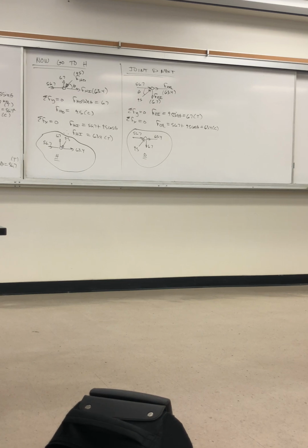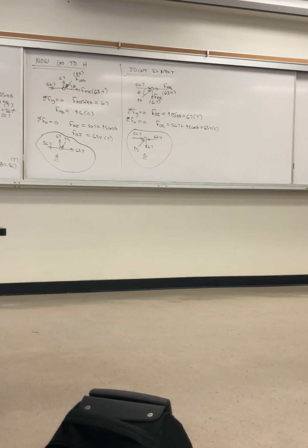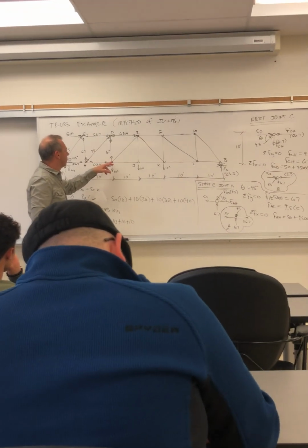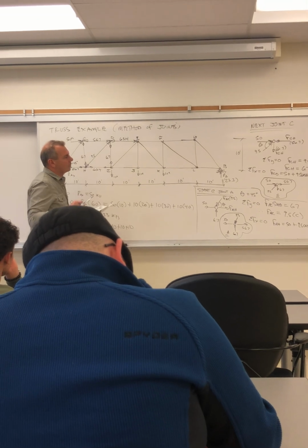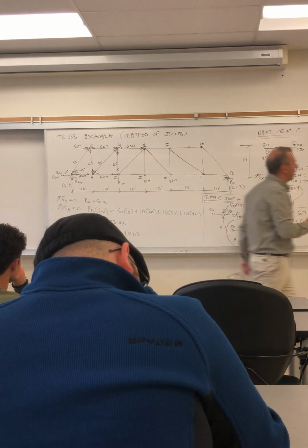So we've been diligent about transferring the forces after each joint to this. Otherwise, if we forget to do it, then it would be confusing and a mess. So we still have two or three more that we want to do. Next, we actually go to I now. Even though I initially had 1, 2, 3, 4 unknown forces, we now have 2 less. So we have 2 unknown forces. Let's put I next.